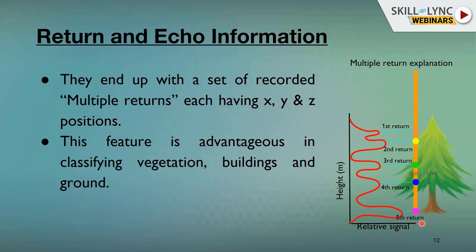When we are collecting the data from airborne lidar or mobile lidar or drones, it will give single points, by default in one class. Now I want to segregate them into multiple classes, or classify the data into different layers or different classes. Let's say I have point cloud data for a particular location, like a settlement area, and my client is asking me for different classes in this point cloud data. What I can do is select the particular returns and classify the data.